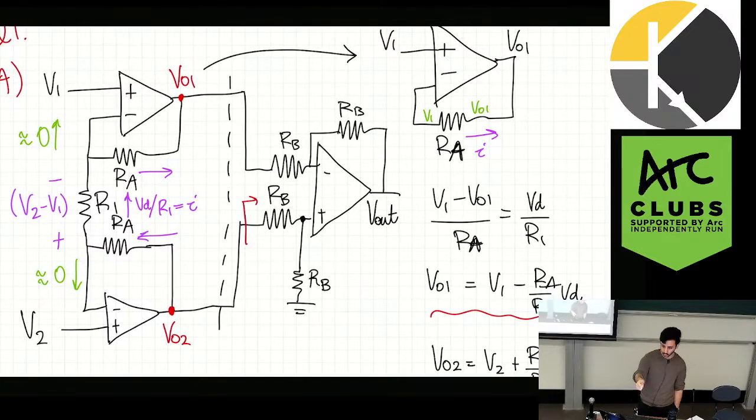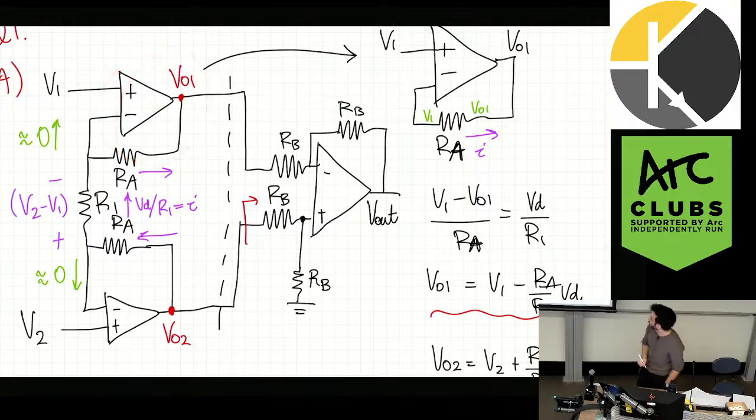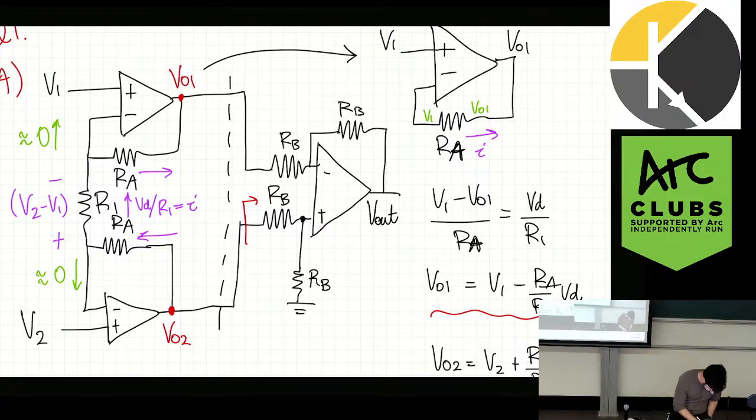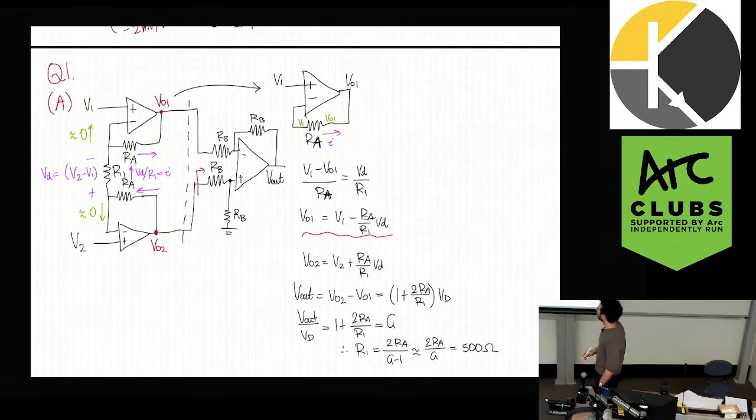what's the difference? So you mentioned one point, the buffer? I said the difference between the previous part and this overall circuit is that you have a buffer, and the buffer helps us with common mode rejection because we're not reliant on all of these being exactly the same. Yeah, exactly. So we're just less dependent on these resistor values, right? We have these pre-buffer stages, which give us the gain and also buffer the signal. You can also look at it from the formula, like Vout1. I don't want to overcomplicate it. Does that make sense?